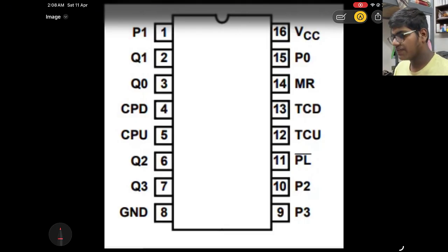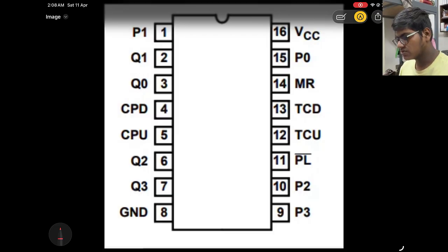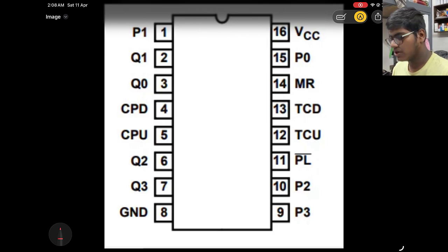Internal working of the IC 74HC193N that we have used in our project. It majorly consists of 4 flip-flops and multiple logic gates like AND, OR and NOT to control the logic for counting up and down. These flip-flops can store 1 bit of data, and when a pulse is passed through CPD or CPU, the flip-flops toggle one by one continuously.